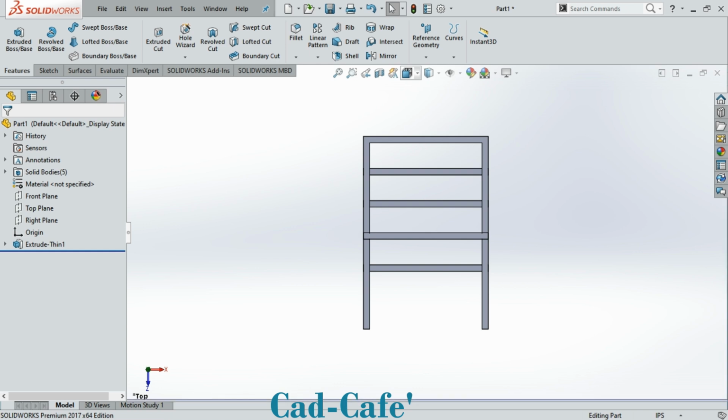First of all, you see the top, right, left, the front, and mind you, attached to these views you see the shortcuts. For the front you see Control 1, the left is Control 3, the top is Control 5, the bottom is Control 6, the right is Control 4, and the back is Control 2.